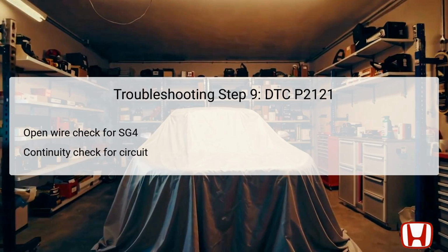In this final troubleshooting step, focus is directed at checking the SG4 line for potential open circuits. Initially, the technician powers down the vehicle and prepares to start the SCS again for proper diagnostic conditions. After disconnecting the PCM connector, a jumper wire is connected to verify the integrity of the SG4 circuit through a continuity test. The expectation should yield continuity readings indicating that the wiring is intact throughout its path.